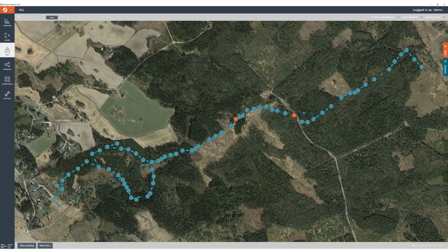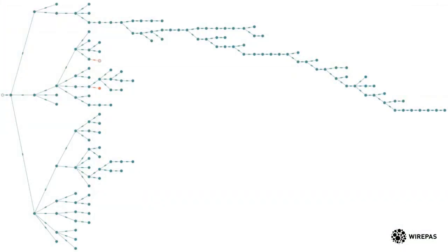As you can tell, there are lots of single point failure opportunities in this network if it doesn't self-heal or automatically reroute. So this is one of the places we use to test. You can see we have a couple red dots in here, which represent some of our nodes with low batteries, and they alternate, forcing things to automatically self-heal. So from a topology perspective, this is what that network looks like and how it routes data from an end device all the way up to the sink, which is the far left node.